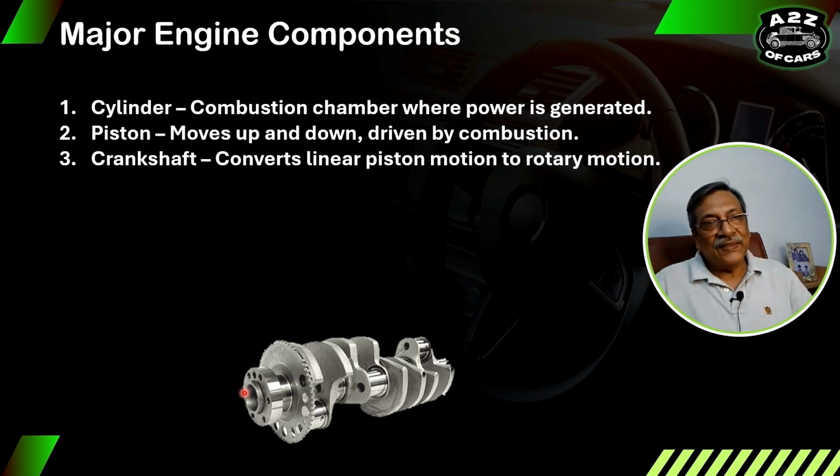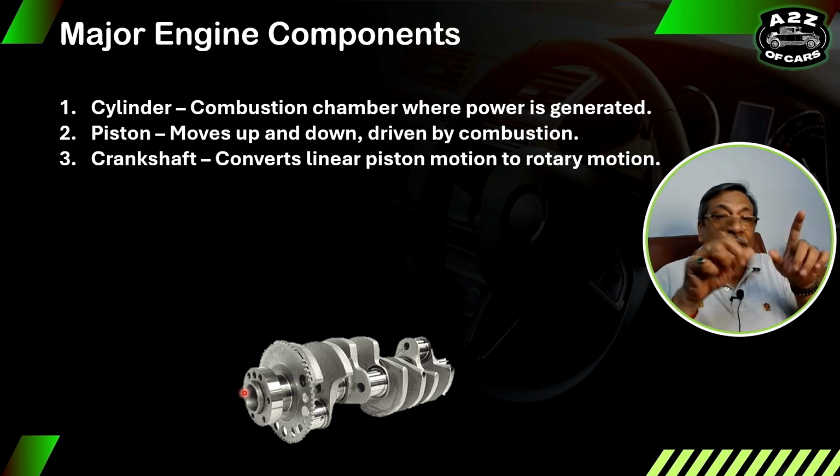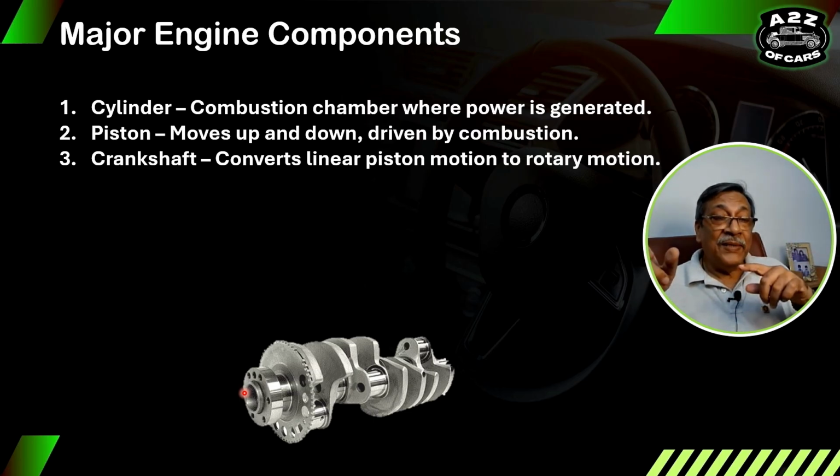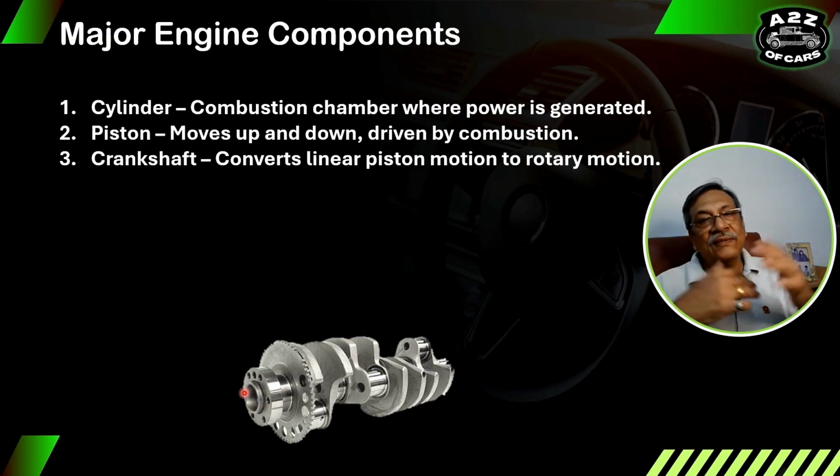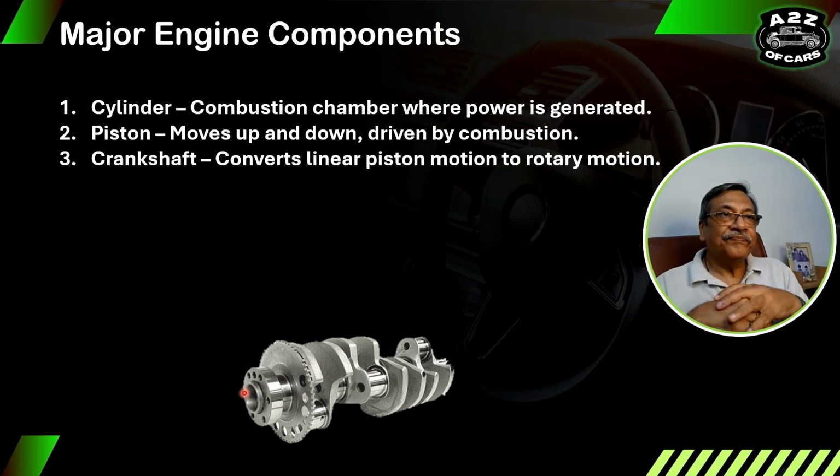the cycle pedals. But because there are 4 pistons, 4 cylinders, in one power is happening, in one intake is happening, in one exhaust is happening, in one compression is happening. So that's why the location of all the 4 is in a different way.